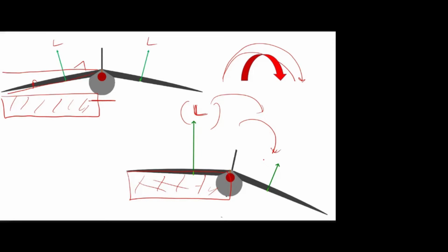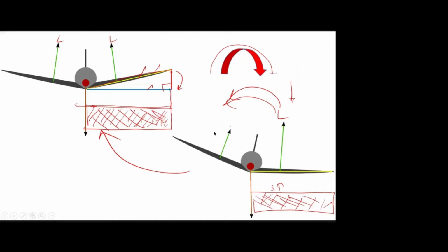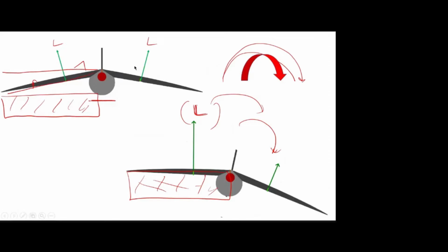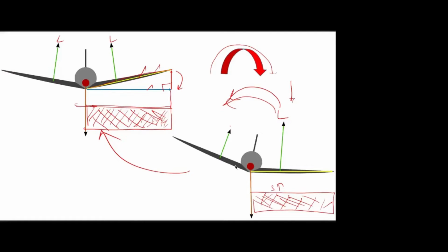Okay. This type of rolling maneuverability is needed only in fighter aircraft. So we are going for this anhedral type of wing in fighter aircraft, not in commercial aircraft. If you use it in commercial aircraft, it will be very difficult to stabilize the aircraft, and it may fail. Dihedral is the stable configuration we use for commercial aircraft. Anhedral is very unstable, so it is good for maneuverability. So we are using it in jet aircraft. Is that clear? Anhedral, dihedral.